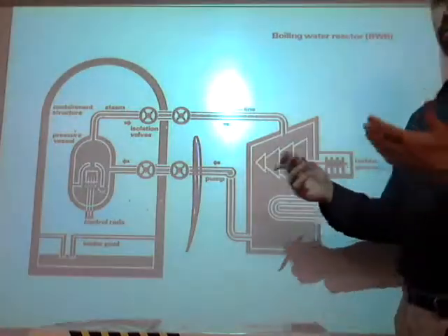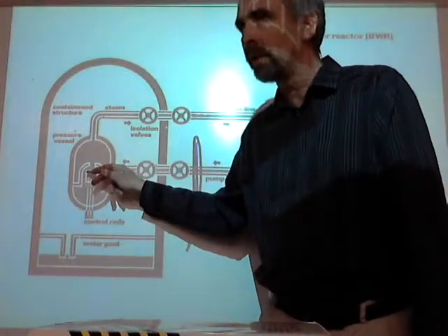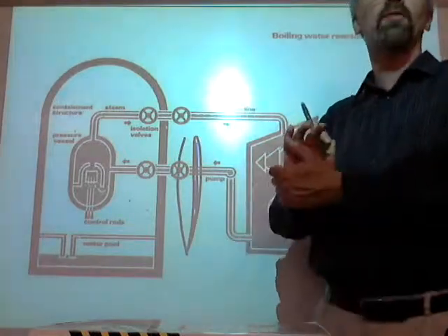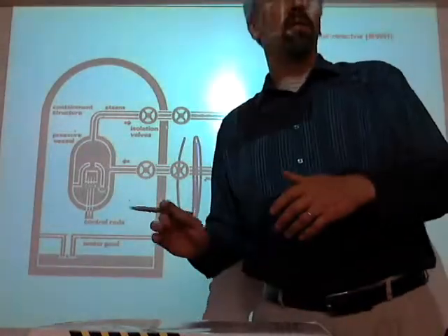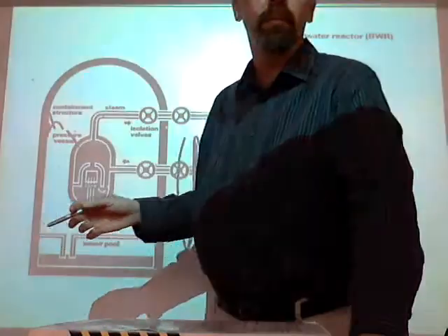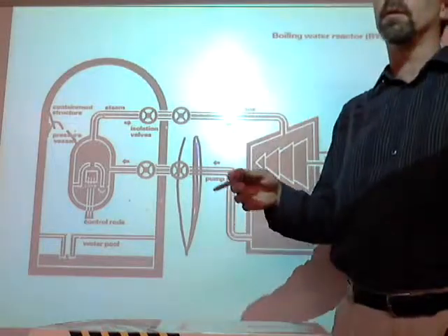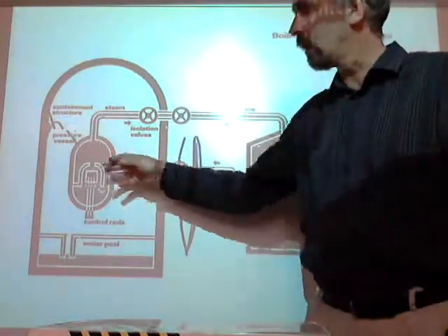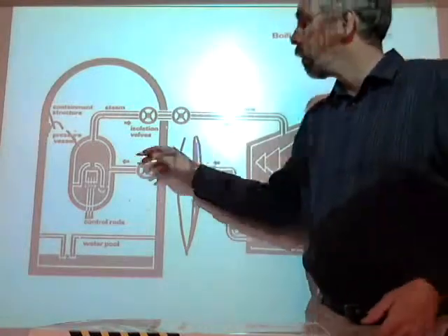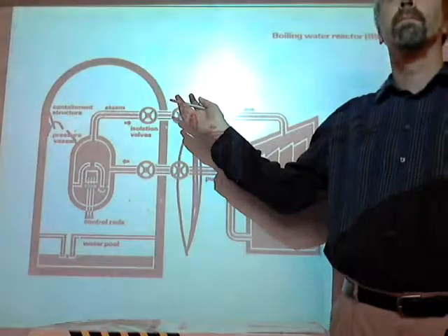Those engineers, those operators, thought that there was too much water going into that core, into that vessel. So we know what they did? They stopped it, cut off the water, because they didn't realize that there was a valve somewhere in here that was stuck open, and water was just leaving and leaving and leaving. Now the plant knew it. The plant said, get me some more water in there, it's too hot. They said, we know better. They stopped it. What happened? All the water left the core, pretty much exposed the core.